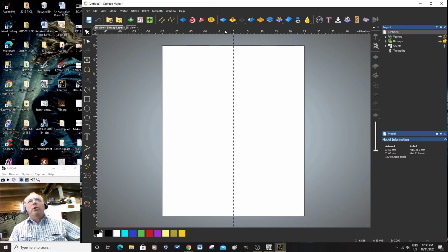So what I'm going to do is go up here into the X ruler area, click, hold down, and fetch this down, so that's 30, that's 10, 20, 1, 22, right there. So that means if this is 30 millimeters there, I want an 8 millimeter offset from the center.